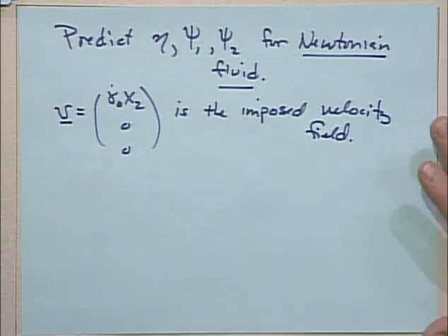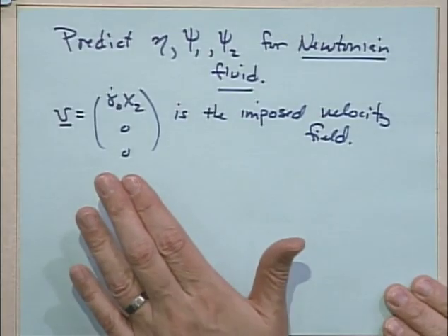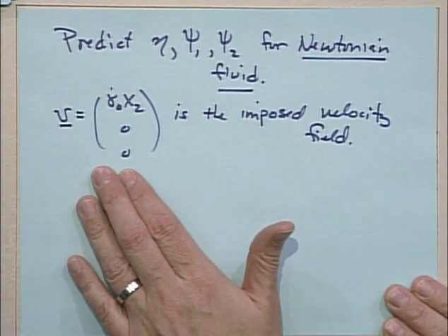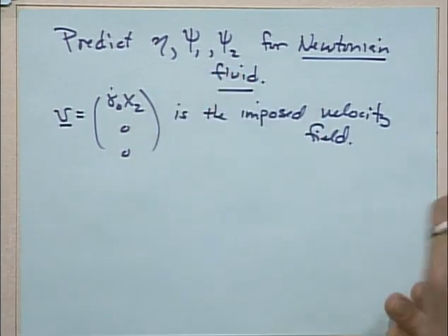So this is totally different from the idea of solving for the velocity field. When we solved for the velocity field, we said, take a Newtonian fluid and put it in this situation. Put it between two infinite plates and move one of the plates. Put it between two infinite plates and blow on it with a pressure difference. Put it on two upwardly sloping plates. Run it down a wall. Put it between a cup and a bob and turn the inner cup. Those were all flow situations, and we said solve for the whole velocity field. Right? That's one use of constitutive equations, and the momentum balance. Here we're saying this is the velocity field. Predict things that are related to the stresses.